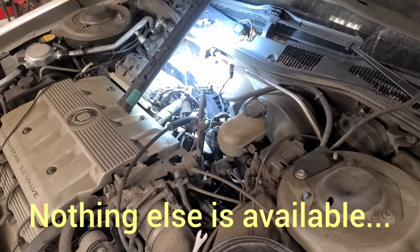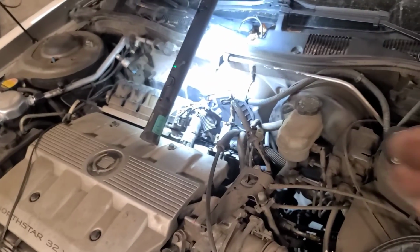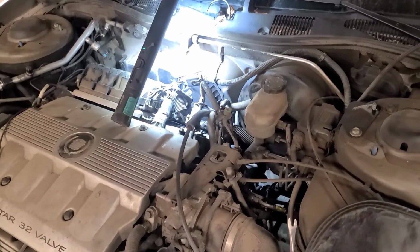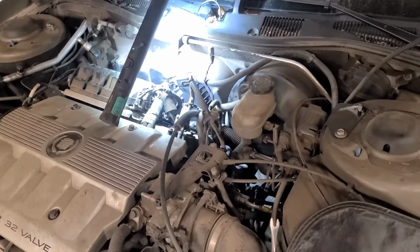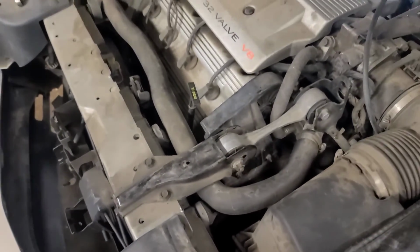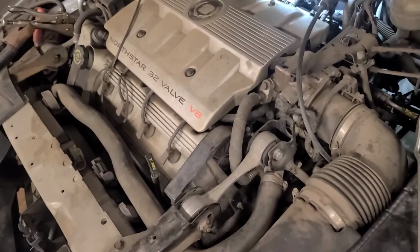So I got the aftermarket one in there. I had to use a die grinder to grind the hole a little oval so it would allow it to go in like this. And that bench tested and worked, so it should work. It's back together. I used the ratchet strap to pull the engine forward about 3/4 of an inch. That's as far as it would move. So let's see if it works.